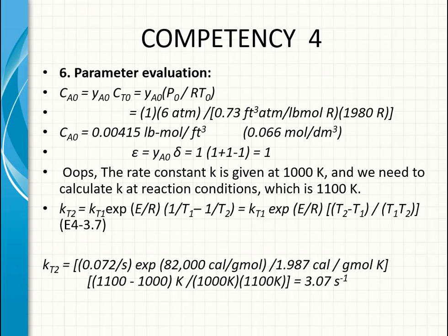So we will have that CA0 is equal to 0.00415 mole pounds per cubic foot. Epsilon is going to be y0 times delta. y0 is 1. Delta is 1 plus 1, remember that it is an increase, minus 1, which is equal to 1. So epsilon is equal to 1.